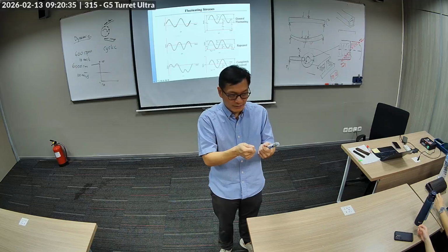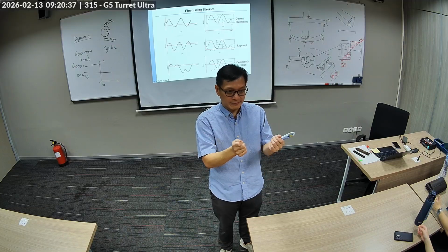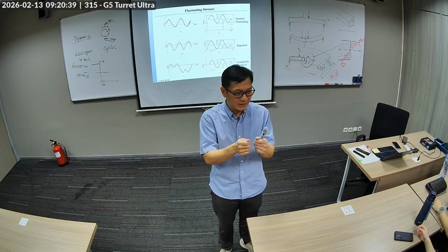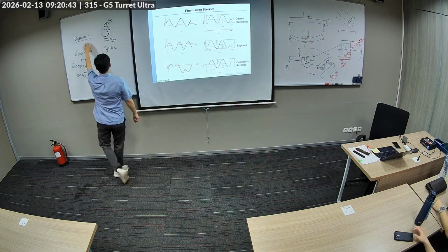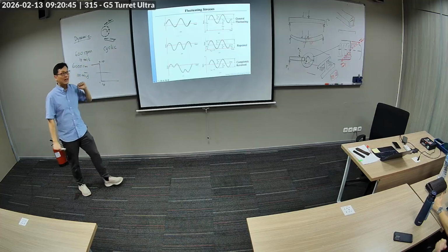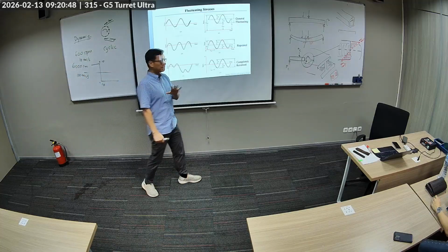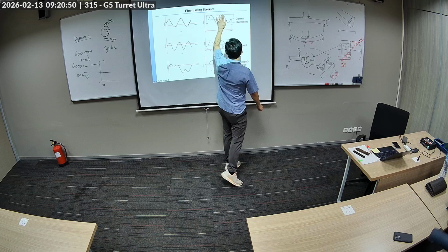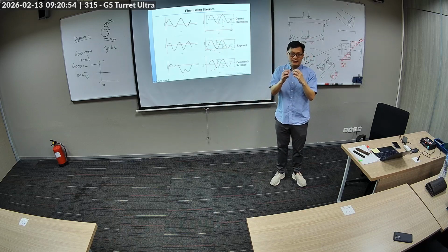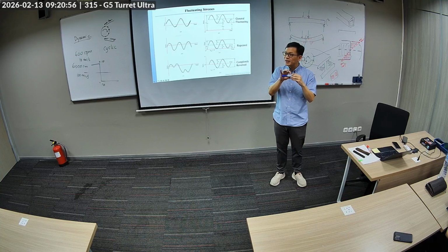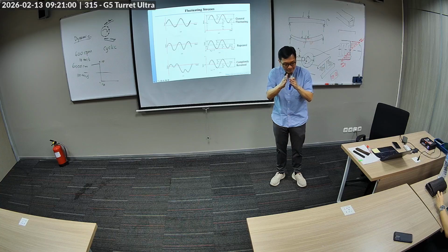First few bends, it doesn't break, and then suddenly it does, even if you bend it a little bit. So that's dynamic stress or dynamic failure, not static failure. And what happens is that this fluctuation creates micro cracks on the shaft, and the crack starts to be cycled and propagate.